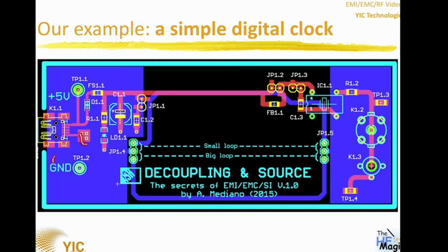So remember, this is a 5 volts line powering my device, and the return GND trace is in the lower part of the drawing. The output of the system is a clock signal that I am not interested in analyzing, but we will see what happened in this signal in the scope. So the first thing to do is to power the circuit and to see how is the clock signal and how is the VCC that is powering the device. Clock signal will go to channel number 1, VCC will go to channel number 2.